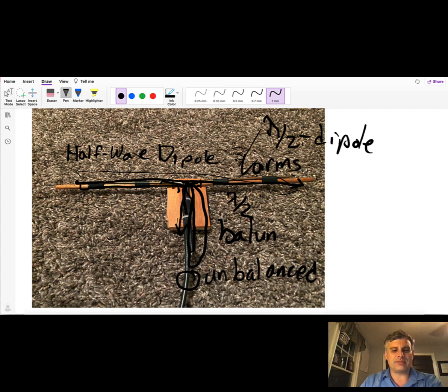This isn't something you normally talk about in transmission line theory. You assume that you have a coaxial cable that's fairly well behaved, where the inner conductor is always carrying the exact same current as the outer conductor. Now keep in mind that the outer conductor current is distributed across a much larger radius. But in theory, if this is operating the way a transmission line should, at any given point along this distance, even if you have standing waves, there's going to be the same peak current this way as this way.